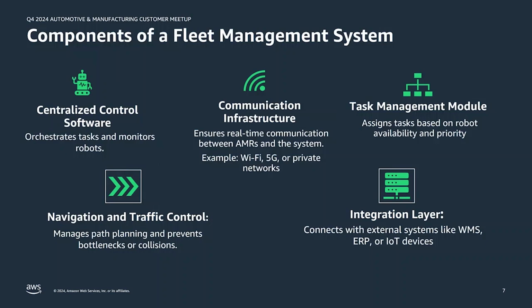Then it serves as a communication infrastructure between them. As I told you, there are use cases where a particular customer could be using AMRs from different vendors. In the absence of an FMS compliant with VDA 5050 standards, there would have been a middle layer or middleware making sure the two AMRs from different vendors are talking to each other. But with the help of these FMSs, the integration between the two becomes much simpler.